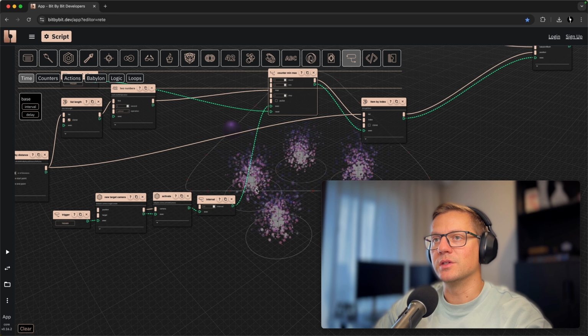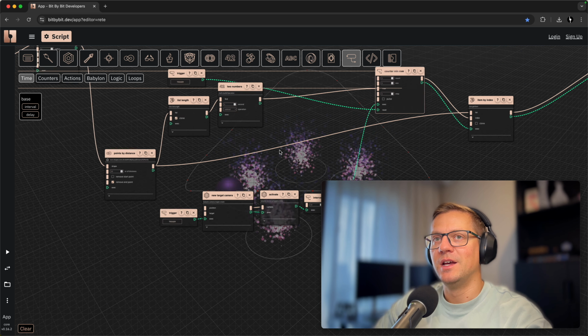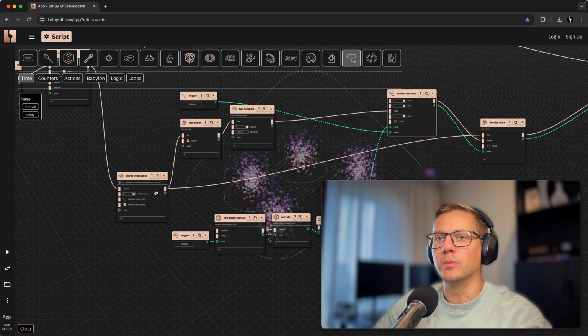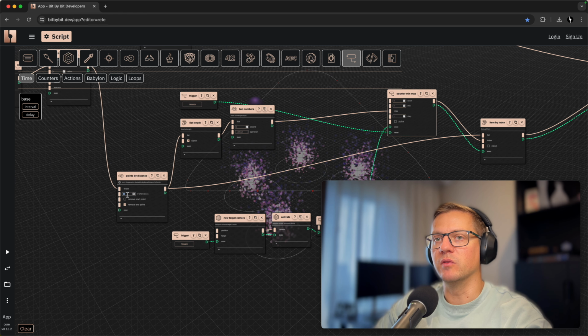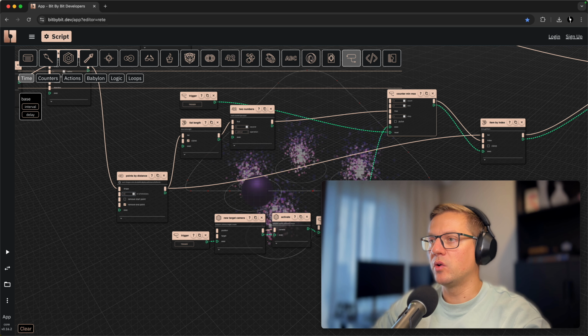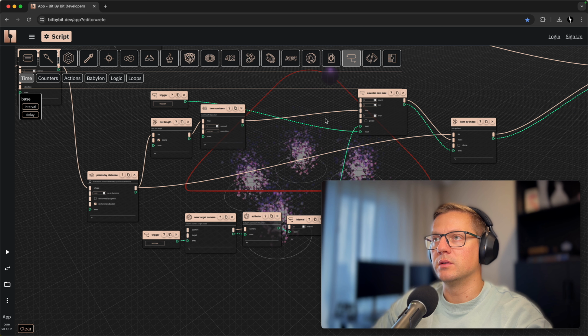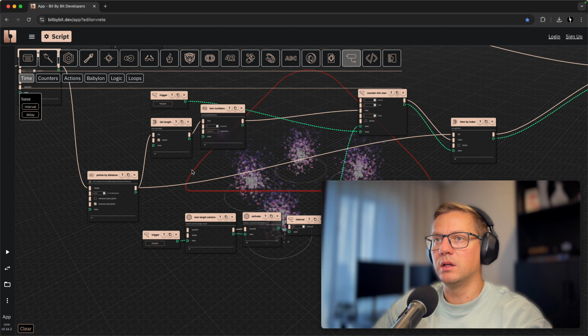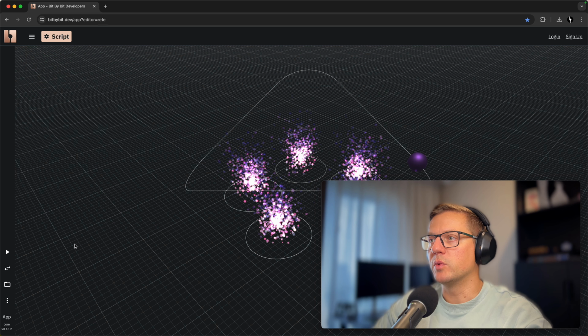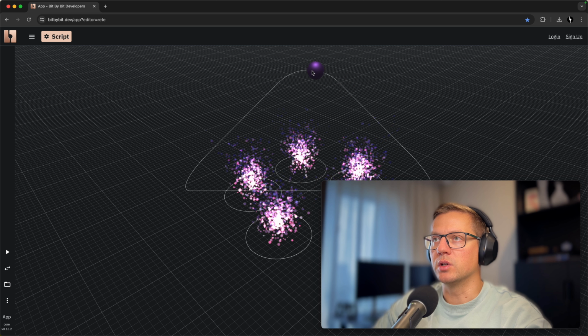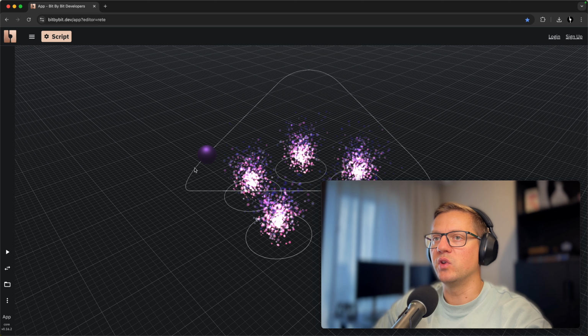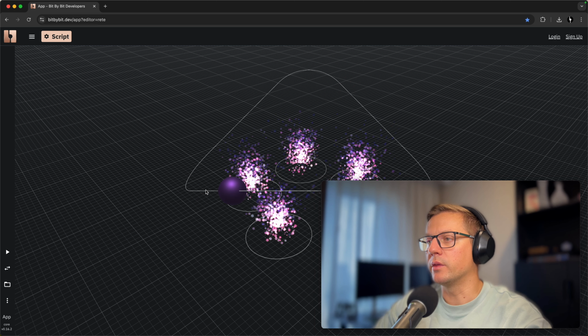You see that the sphere is really moving fast, and that's because we had only 20 subdivisions for this path. Let's create 1,000 subdivisions. Yeah, now it's good. Now it's rotating, and we just need to hide those points. We don't really need to represent those. So this looks much better. The position is changing smoothly, and the sphere just moves along the path.